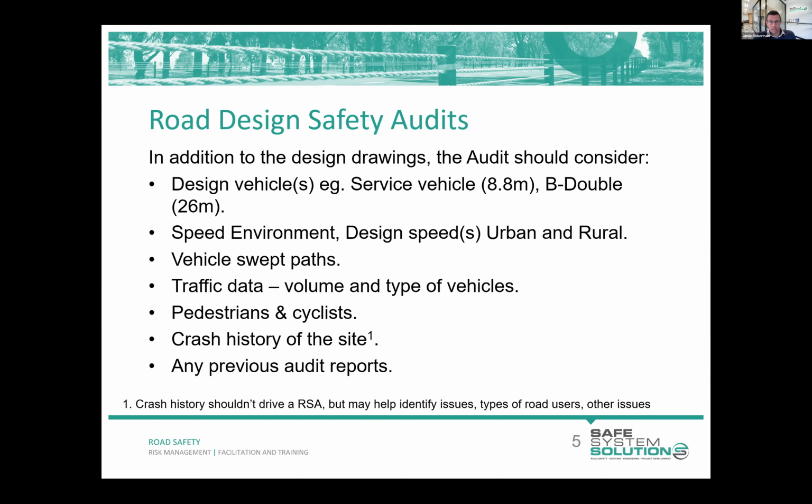If audits have been undertaken previously, and if it's a large project and we've been charged with doing a detailed design stage audit, it's likely that an audit has been undertaken at an earlier stage as well. So it can be useful and educational to see that report, check off which of the issues in that report have been addressed, whether any remain, whether you agree with those issues in the first place. On top of those things, I encourage all auditors to seek any information from the project manager or designer that they feel they need to have to understand the design intent.